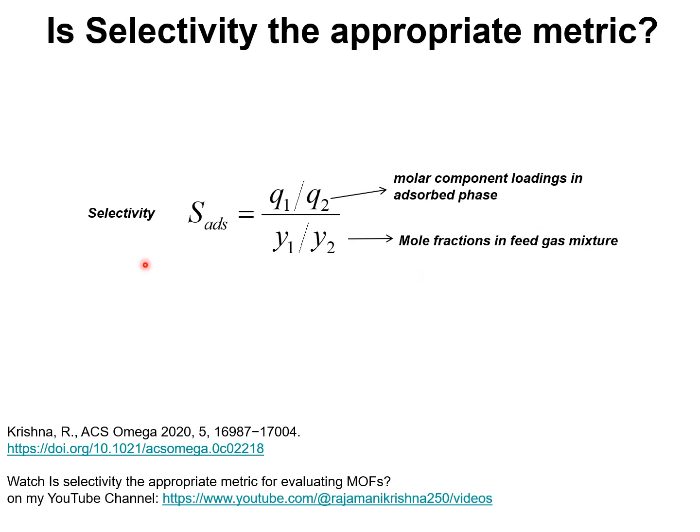The important drawback of the use of the adsorption selectivity to rank and select MOFs is that for separations in fixed bed adsorbers, the adsorption selectivity is not the only factor that determines the separation performance. Indeed, other factors such as uptake capacities are also important. So how do we choose the appropriate metric for natural gas purification that has 3 components in the feed mixture?